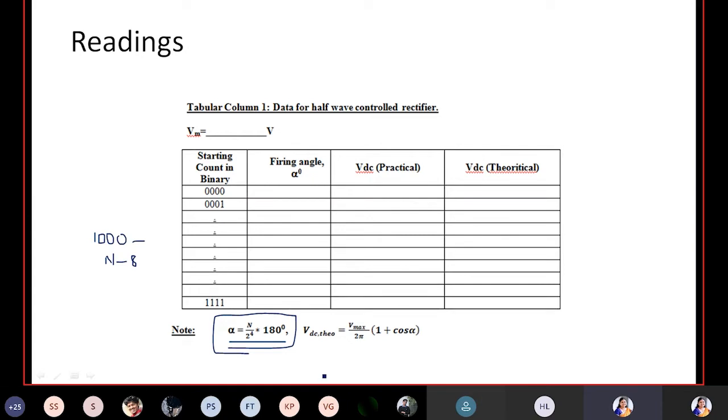Yeah, Rishikesh. Harshal. Yes, ma'am, I've checked it, ma'am. Here they have given that when both inputs are 1, the output will be in an invalid state. It goes to a metastable state where they couldn't predict the output, ma'am. In a JK flip flop, the output will toggle, ma'am, 0101 like that.